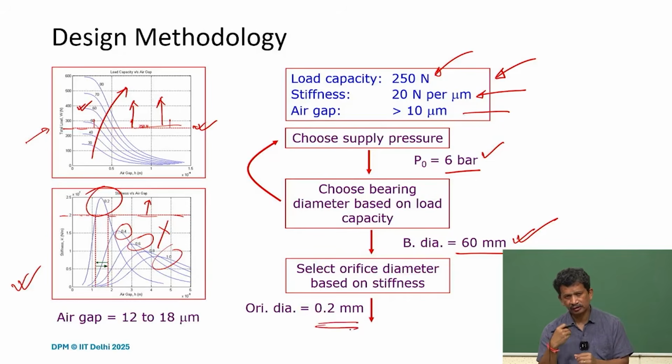So I think while working with these kinds of systems, one has to really fine tune and understand these values and these numbers. So it's not about millimeter or centimeter, but many times it's 0.1, 0.2 millimeters, with an air gap of the order of micron.